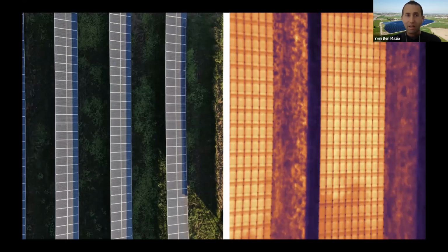In most cases, we also recommend that the asset owners or the O&Ms clean the site before the inspection, because the platform can detect anomalies as a result of soiling, droppings, sometimes automatic robot machines stuck on the modules, or hoses, or some dirt on the modules. Clean the site. We want to detect the internal anomalies in the modules, so that it can help you solve issues with the modules themselves.